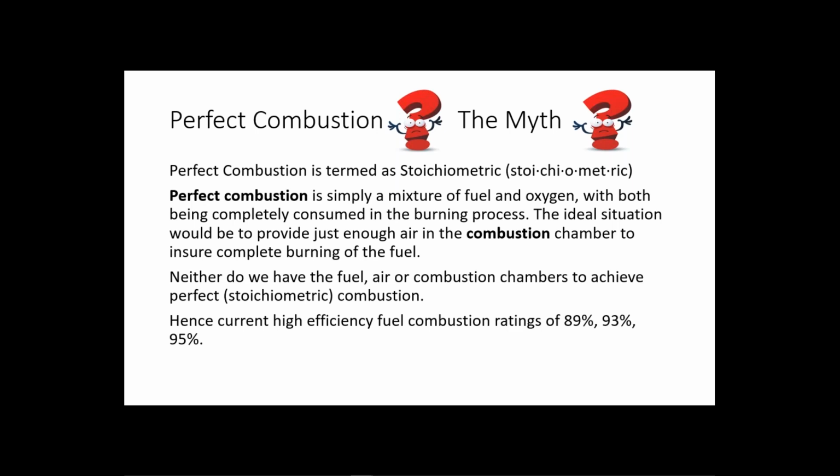I hope in my day, before I'm done, that we do get to see 100% combustion. Not sure that we ever will. It depends on the fuel, and it depends on the design of combustion chambers. Also, our air has a bit to do with it as well. So not being able to achieve stoichiometric or perfect combustion, that's why we're seeing high efficiency fuel combustion ratings of 89%, 93%, 95%, and slightly higher.